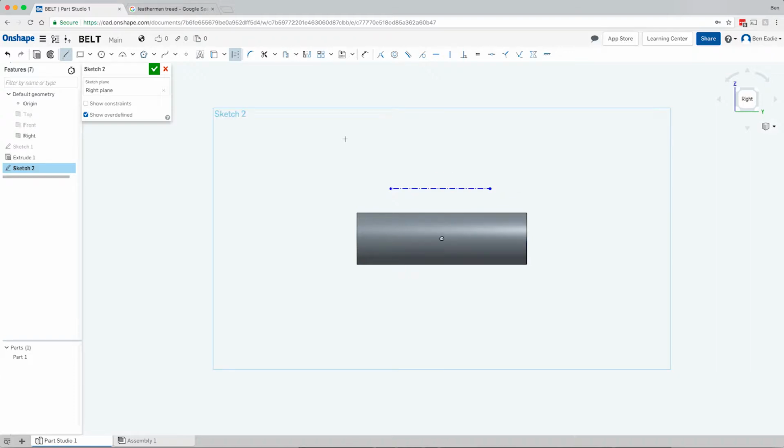So there are some little tricks to go with the line tool. There's click and drag, and then there's click, move the mouse, and then drop the next line. I'm going to show you the difference between the two. Now if I click and hold the left mouse button when I'm making a line, and I come out and release the mouse button, it'll drop that last point, and you'll notice that it is a single line out in the middle of space on its own.